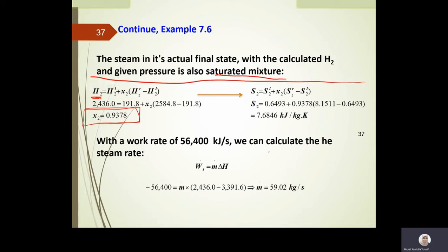But this step that I did here is just in case they ask, for example, to calculate S2 at the outlet, or U2, the internal energy, at the outlet, or the specific volume at the outlet. You have no problem, because once you have the quality, you substitute in the main equation: any property M you want to calculate is equal to M liquid plus X times M LV, or delta M LV based on some textbooks' definition. That's basically what you have to do.